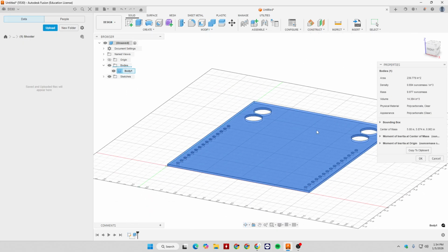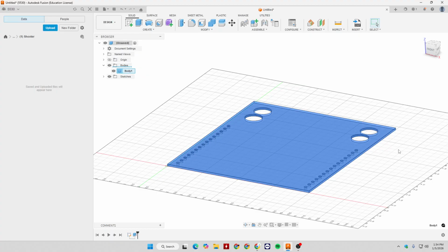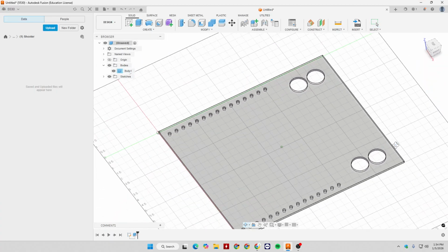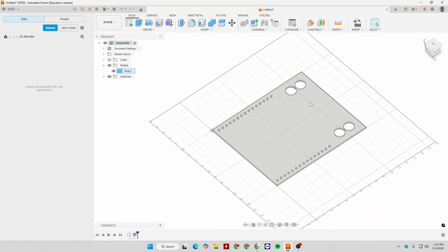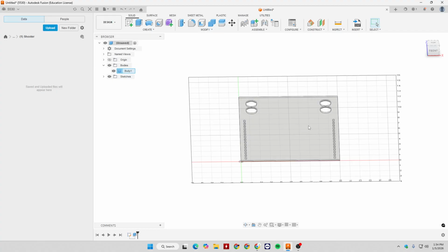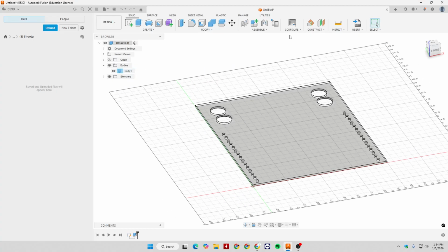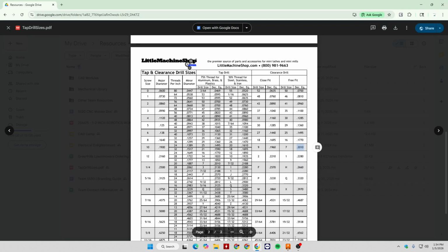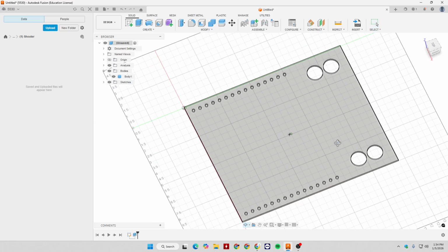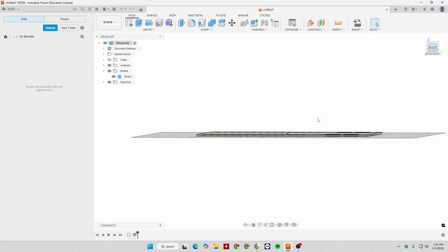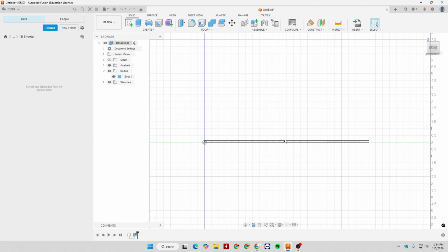Now, these are really important when we're doing center of gravity calculations for our robot. If we're hanging, or if we're trying to make sure we're under the weight limit, doing this for all of our parts is very important. So, for example, if we go to our inspect feature and display the center of mass of this piece, it'll calculate exactly where that's going to be, and you can see it's kind of in the middle of this plate.